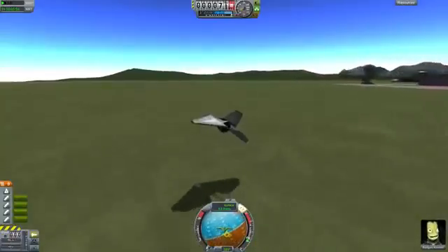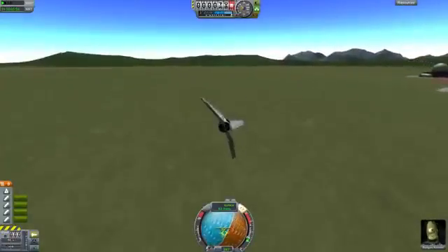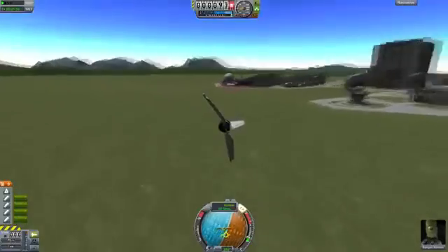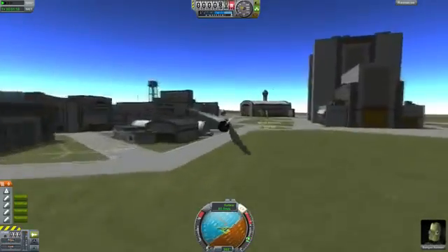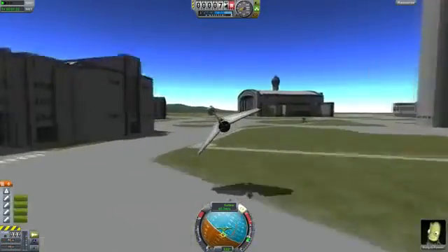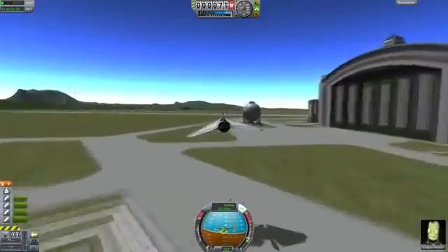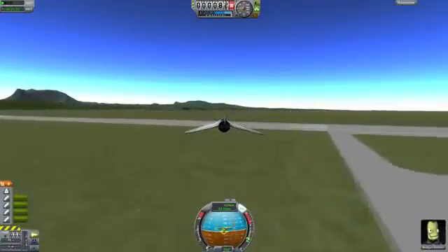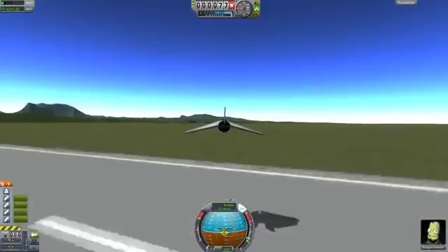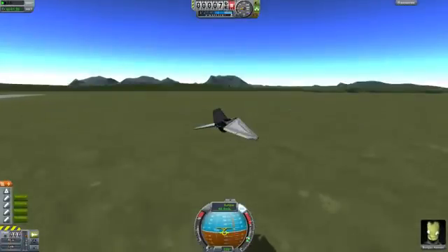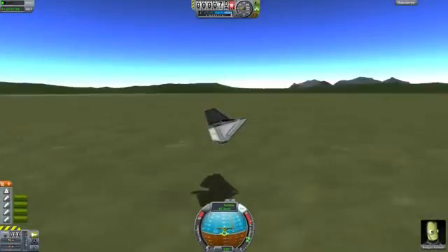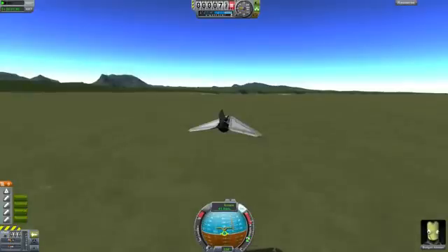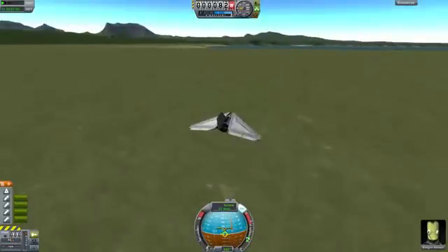We've essentially discussed aerodynamic stability, configurations of wings. The principles are you want to put your wings on, you want to look at where the center of lift is, and you want to make sure that the center of lift is slightly behind the center of mass. Always. If it ever moves in front of the center of mass, you're going to have trouble controlling your vehicle. You want to make sure you have vertical stabilizers. It helps if they have control surfaces, but it's not absolutely essential. Wings tilting upwards will tend to make your aircraft more stable. Having the tilt downwards will tend to make it less stable, which may or may not be what you want.